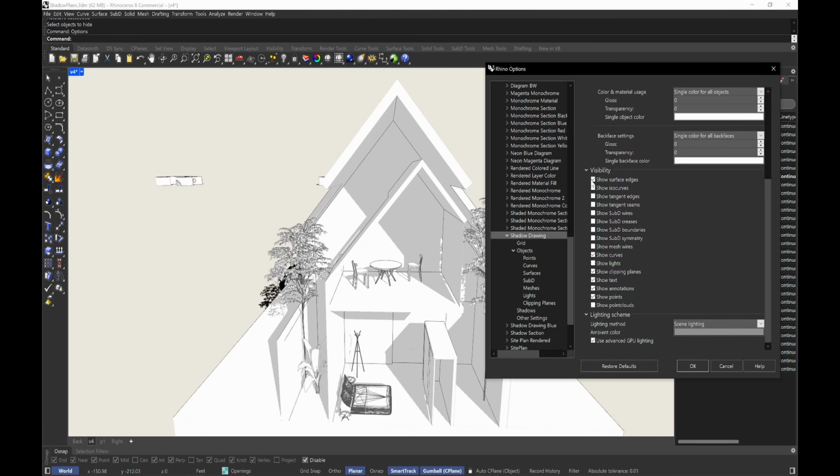I actually wouldn't. I wouldn't show the surface edges. It would just be basically all white. You see, it would just be like that. And then you're just overlaying it underneath your Illustrator drawing. Okay, so this is really important to understand. If you're going to take it to Illustrator, my preference is that I would keep it without any of the edges. So it's just pure shadow and fill, and you just underlay it in your Illustrator.